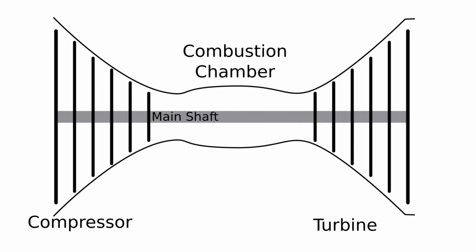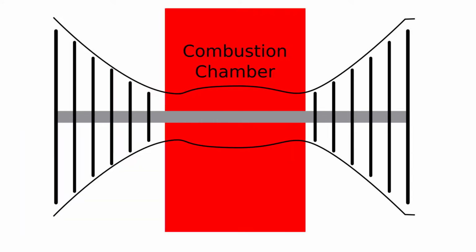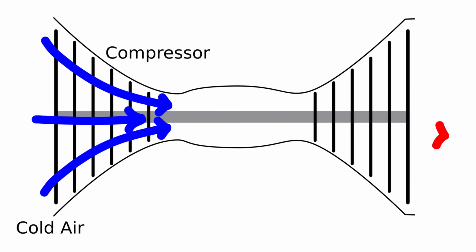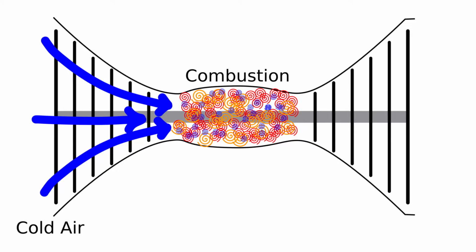and its efficiency. Thermodynamically, the engine has 3 parts: a compressor, a combustion chamber, and a turbine. The compressor collects the air and increases its pressure. By increasing its pressure, it's also increasing the amount of oxygen that's in the same amount of space. So, when we go to burn the fuel with that oxygen, there's more oxygen available for the fuel to burn, making it more efficient.